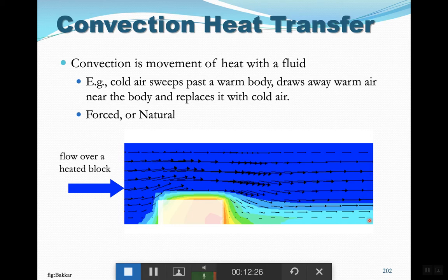So forced convection is first, then you have natural convection and conduction. Always remember that. Anywhere that you have forced convection, you can basically neglect natural convection and conduction. You have experienced this a lot. You have seen this in winter, when you have your jacket on and you're walking outside in cold temperature, minus 20, minus 25, as long as there is no wind, you don't feel cold.